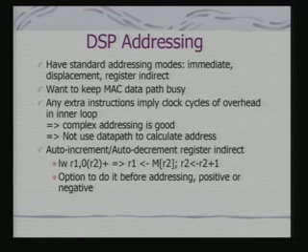These kinds of addressing modes are available: auto increment, auto decrement, and you can do it before actual operations or after actual operations. We have discussed these addressing modes in the context of ARM, and you can realize why ARM implemented this to facilitate this kind of sequence of data access, because here you are actually getting a sequence of data from a sensor.